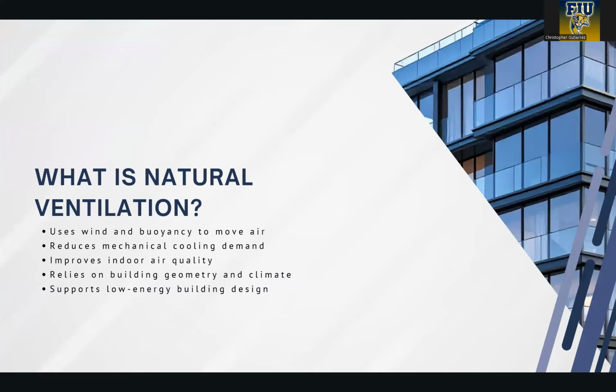Before I go into the structure of the presentation, I want to give a quick background on what natural ventilation is. So natural ventilation uses wind and buoyancy to move air through a building. It reduces mechanical cooling demand and improves indoor air quality by bringing in outdoor air. The process depends on building geometry, opening placement, and climate conditions. When these elements line up well, natural ventilation becomes a stable, low energy strategy.